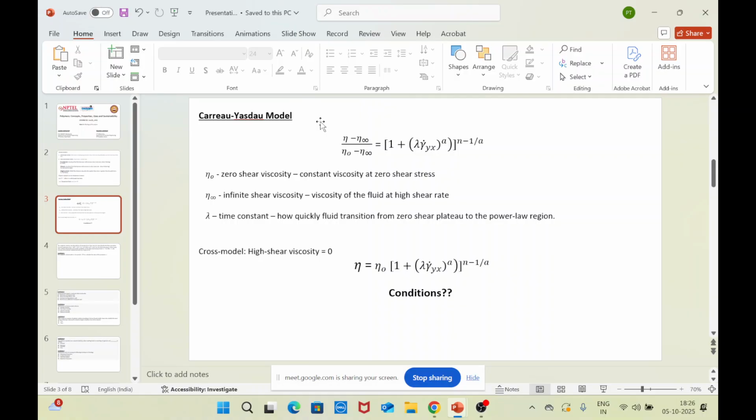So my question is, what is observed in DSC which helps us to know that this solvent plasticizes or acts as a plasticizer for the polymer? How does the DSC convey this message to us that the segmental flexibility of the polymer chain is increased? We discussed this in the previous sessions as well.